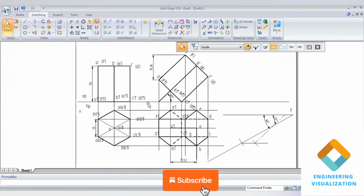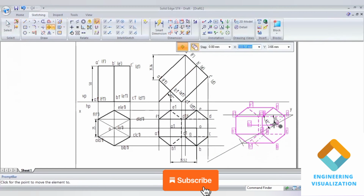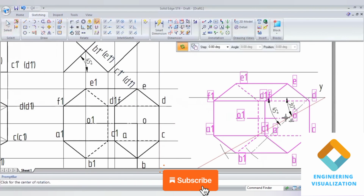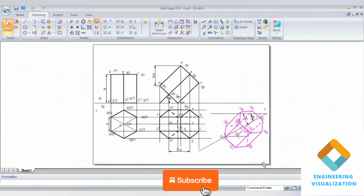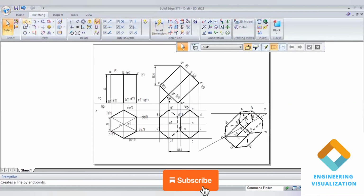Now we need to copy this second position top view and transfer using move command. Okay, project it upward to complete the final position.